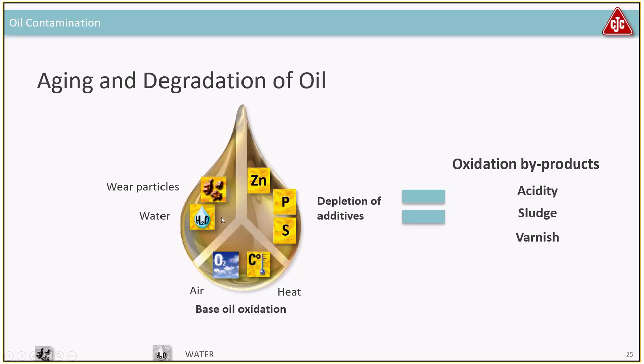The more particles and the more water you have, the faster the oil will degrade. Primarily because the particles are actually creating wear, so you're getting hot spots in the load zone that are getting hot and destroying the oil, and also creating more wear. So it's like an exponential growth of the amount of particles.